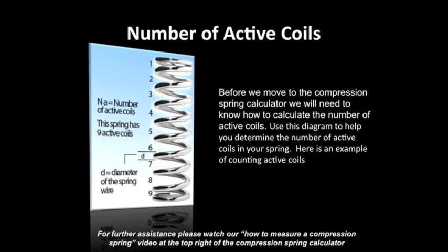Before we move to the compression spring calculator, we'll need to know how to calculate the number of active coils. Use this diagram to help you determine the number of active coils in your spring. Here is an example of counting active coils.